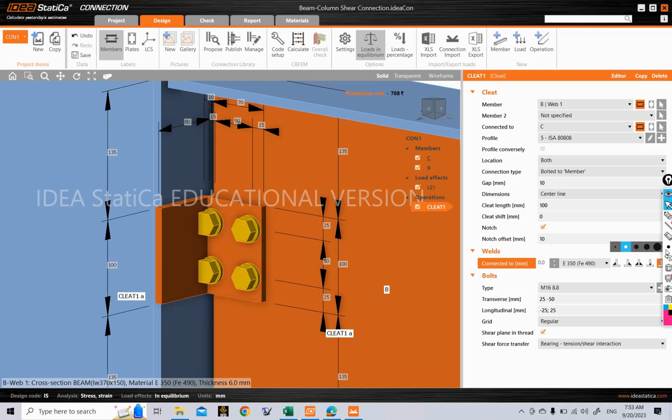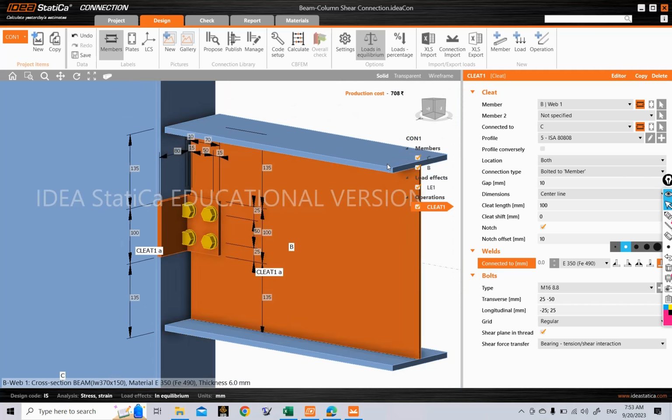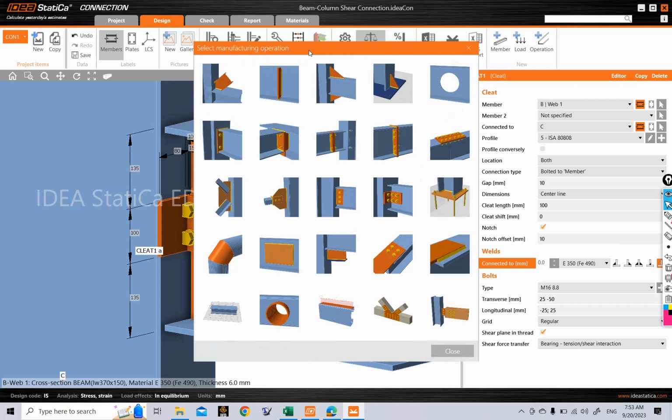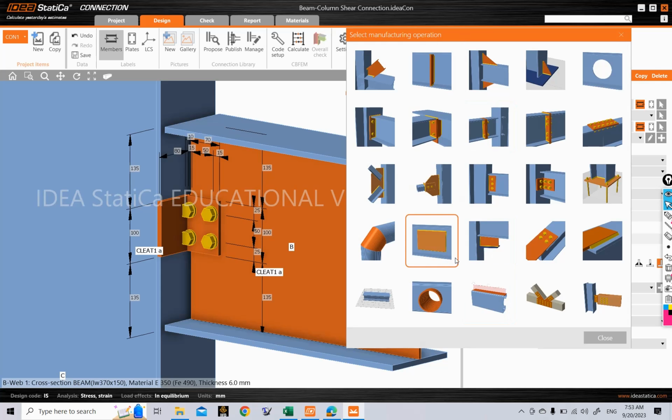So now if we are selecting no weld here, how can we add a weld here manually? To do that, again we have to go to this operation tab at the very top. Now if you click on this operation tab, search for our weld option here, where this weld option has been given. So first we have cut, stiffener, widener, rib, then we can also open a notch or make an opening. Then we have end plate, stiffened end plate, stub, plate to plate, splice section. So there are different options available here.